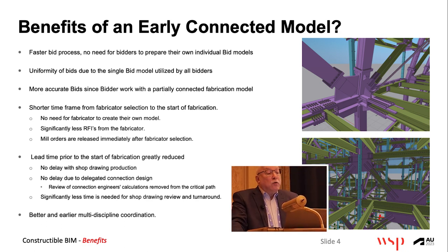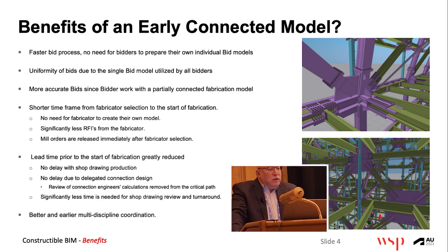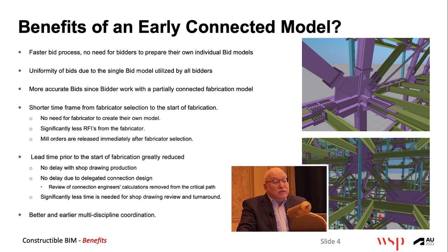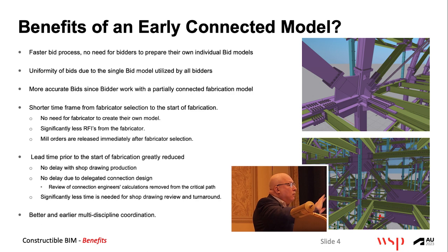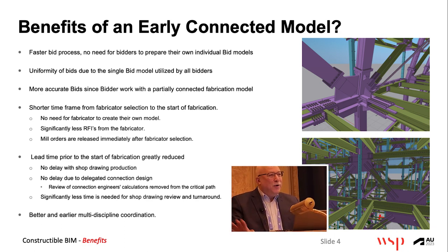And mill orders are released sooner, much sooner. There's no delay due to shop drawing production, and you'll see why. Shop drawings are done way in advance. No delay due to delegated connection design. In conventional jobs, old-fashioned jobs, the engineer walks away, the job goes to the fabricator, they bring on their detailer, and the detailer's engineer, and then the questions and the extras start flowing. And it all gets eliminated.